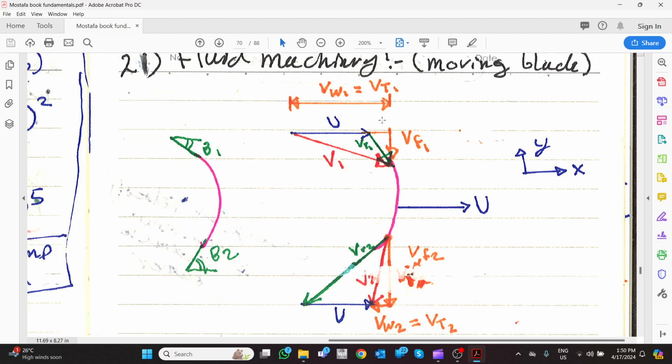And the y component: because the plate is not moving in the y direction, the y component of this velocity is the flow velocity, and also the vertical component of the relative velocity to the plate. Relative velocity in x, relative velocity in y, so you get the total relative velocity on the plate. If you have a tiny person standing here checking the velocity, he will find a flow going like this, with this direction and this magnitude. And somebody outside can see the big velocity.